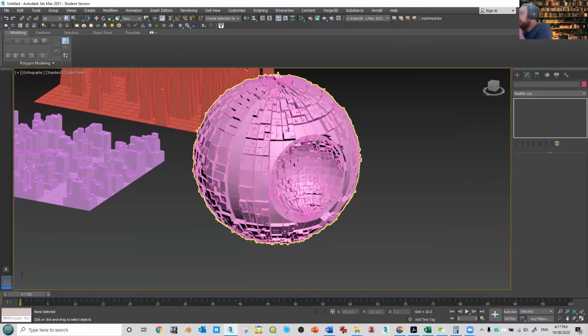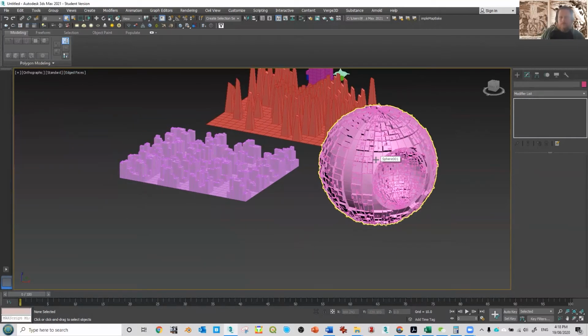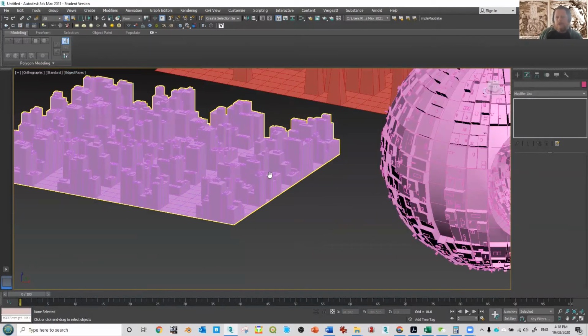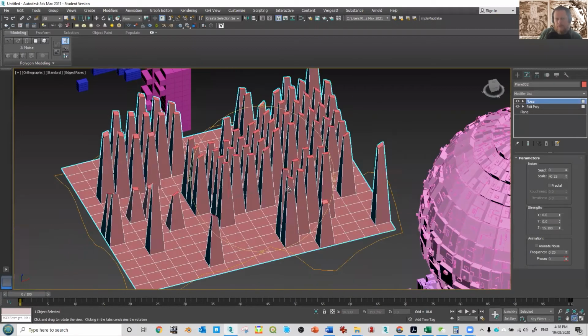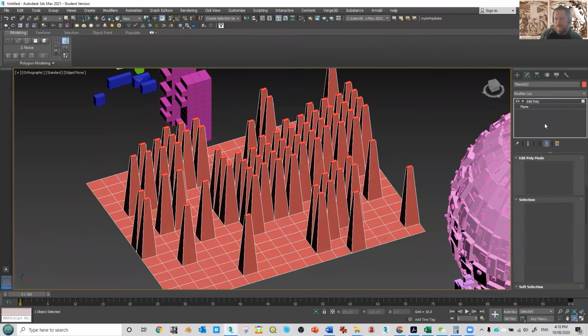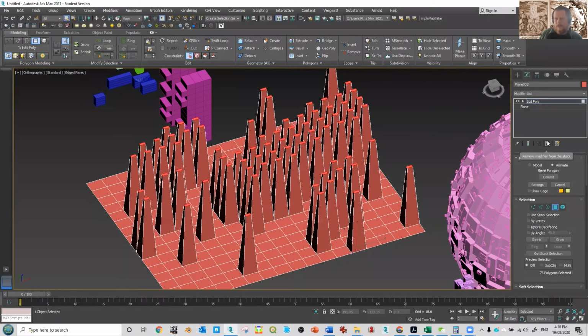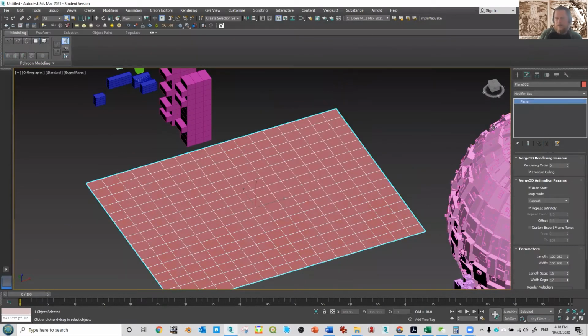And sorry, also about the extrude faces. Let's say we have a residential and a commercial level. Can you adjust the heights individually, manually? Yes, you can. There's a few different ways you could do it. You could do them as separate ones. So if I got rid of that, let's do it again.